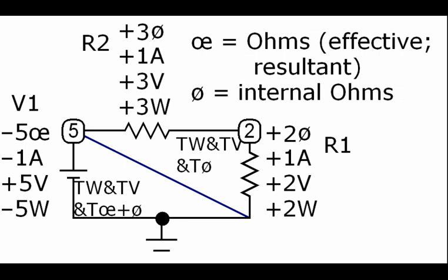But once you figure out what the total resistance is among your various resistances in the circuit, now you know what the effective negative resistance is of the battery. This is all according to passive sign convention, but it makes sense because it is a negative resistor. Negative resistance has the capacity to generate current rather than consume it. So it's not enough to say that under passive sign convention the voltage is positive and the current is negative for a battery.